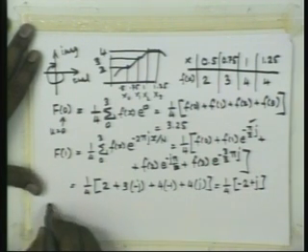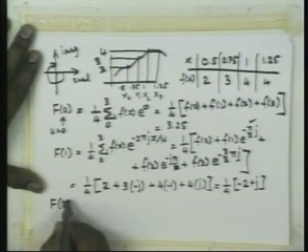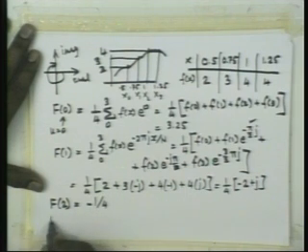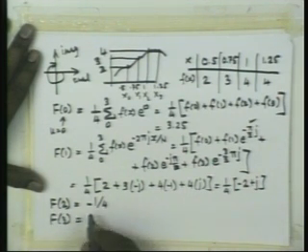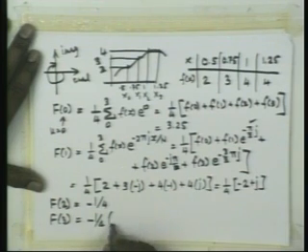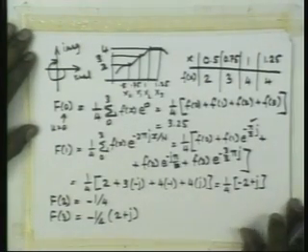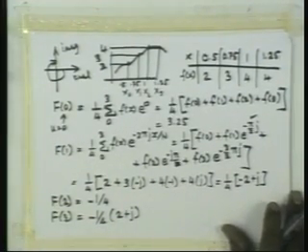Okay. Likewise, without actually laboring over it, let us say that we find F2 turns out to be minus 1 over 4, and F3 calculates out to be minus 1 over 4 times 2 plus j. Okay. So now I have determined all the values of the spectrum, which is represented by capital F0, capital F1, capital F2, and capital F3. Okay. So I can plot that.